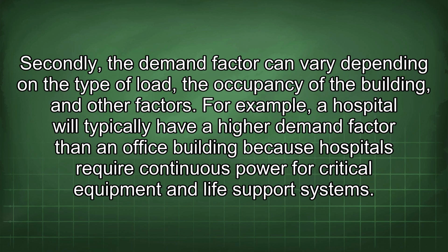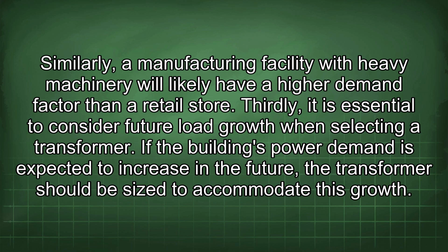Secondly, the demand factor can vary depending on the type of load, the occupancy of the building, and other factors. For example, a hospital will typically have a higher demand factor than an office building because hospitals require continuous power for critical equipment and life support systems. Similarly, a manufacturing facility with heavy machinery will likely have a higher demand factor than a retail store.